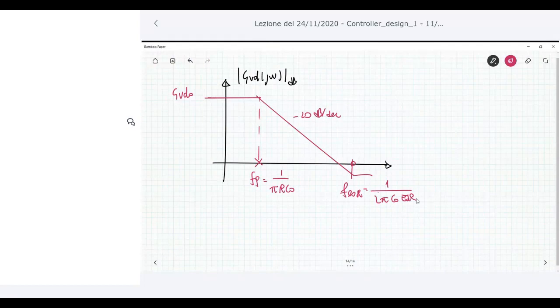The gain for the buck boost is given by V in multiplied by R over 2 L FS. We derived this expression using the circuit averaging techniques. Okay, this is constant. This is the frequency. So we have just 1 pole, but this pole depends on the resistance.